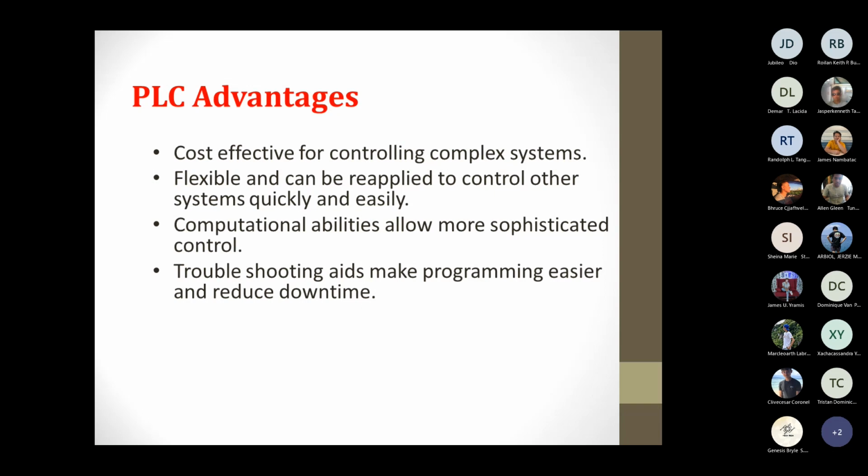So meaning to say, if there is, let's say, trouble, using the relay logic would be a very tedious task. So you have to know which part of the overall relay system is being damaged, or being corrupted, or malfunctioning. But in the case of the PLC, since it is done virtually, that means your wiring cannot encounter loose contact, it cannot encounter broken wire, because it is done virtually.